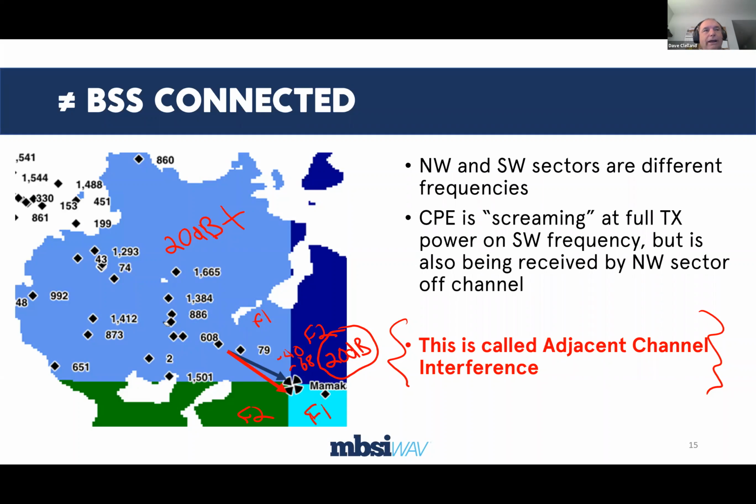And that's why with lots of systems, you can put 10 or 15 or 20 subscriber modules on a sector, but you can't go any more than that, because now we end up with a problem of this noise floor coming up too much. So you've got to add another access point. You add another access point, and you've increased the noise floor again by a certain amount.